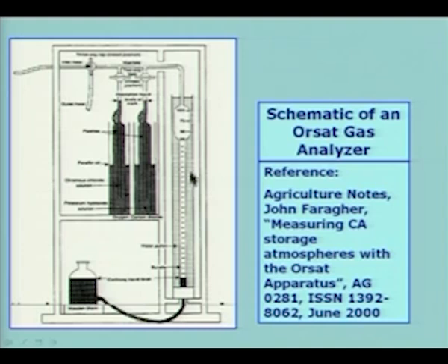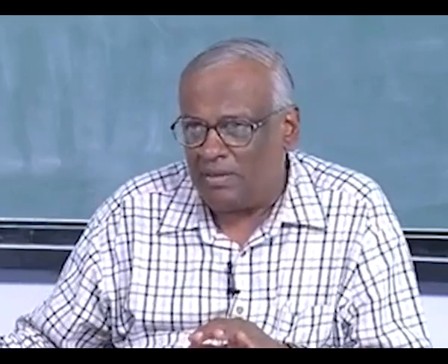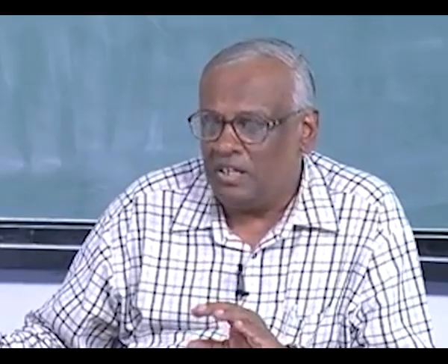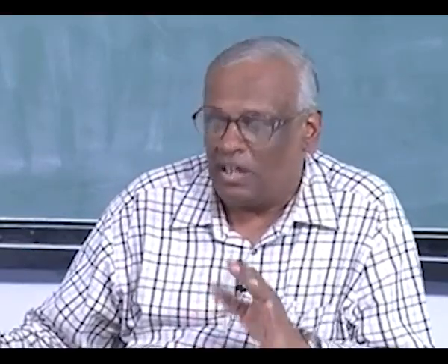The third point I would like to say is that because the liquid contained here is water, the entire manifold here and the burette and so on will be fully saturated with water vapor, because there is enough water available for that, and therefore, the measurement is on what is called dry basis, because we are not taking into account the moisture which is always there.